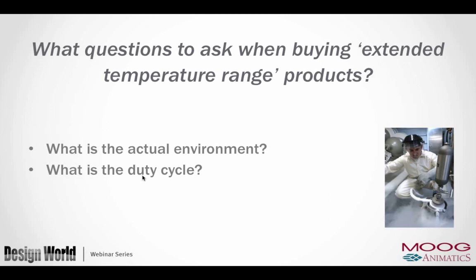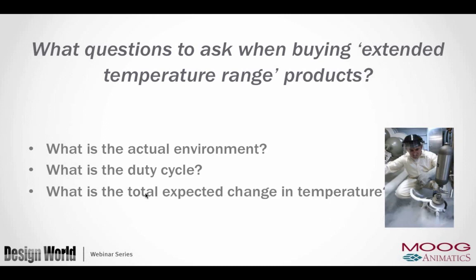Okay, if the environment is very warm outside of an oven or in an oven perhaps, or anywhere where it gets extremely hot, which may be Saudi Arabia out in the desert, whatever. Okay, how long does the motor run, vice how long is it off? How long is the heating effect, vice how long does it have time to cool down? Okay, that's what the duty cycle is about. Okay, what other things you need to look at?